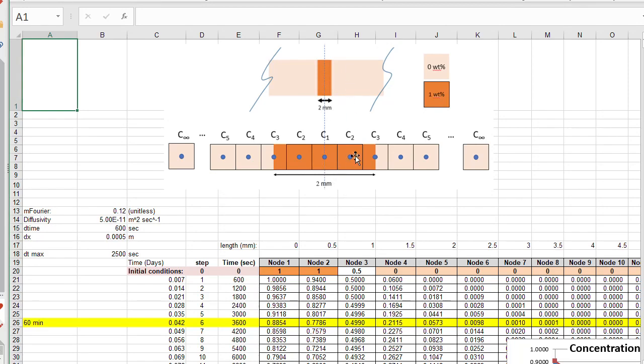So I've got C2 sitting there, and then C3 would put me right on the edge, again of the weld and the sheet. That means C3 is going to have 1/2 of its volume here in the weld layer, and 1/2 of its volume in the sheet. Getting this picture correct and putting the nodes directly on the picture is really your first step in how to interpret everything.